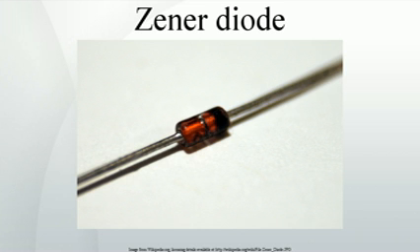In this circuit, a typical voltage reference or regulator, an input voltage, UIN, is regulated down to a stable output voltage UOUT. The breakdown voltage of diode D is stable over a wide current range and holds UOUT relatively constant even though the input voltage may fluctuate over a fairly wide range.